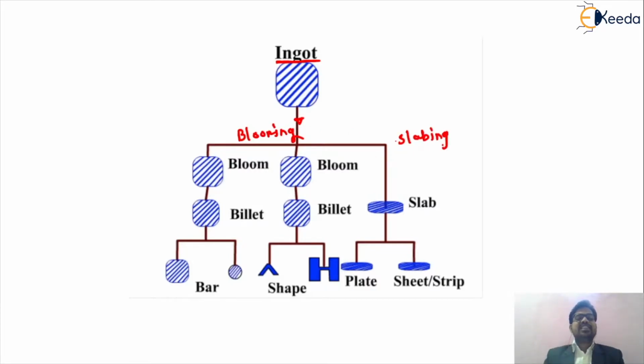Okay, so friends, as we have seen, depending upon the different type of structure that we are getting from the steel rolling industry, we have to use different types of blooming mills. This is the first part of the blooming mill, by which we can convert the blooms into billet sections, and from that billet we convert to different types of bar structure, because different types of civil work and different industries have different preferences. Some industries prefer circular bars, some prefer rectangular bars. Depending upon that requirement, we have to follow this procedure, starting from the ingot to the steel bar.